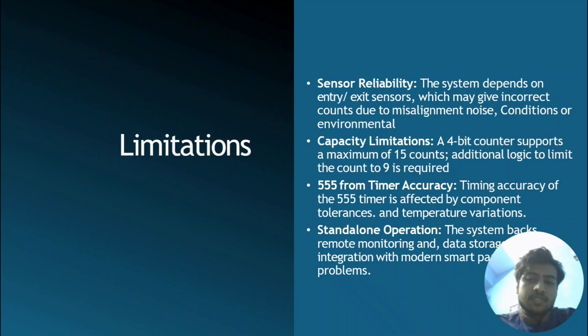Sensor reliability: the system depends on entry and exit sensors, which may give incorrect counts due to noise or environmental conditions. Capacity limitations: a 4-bit counter supports up to 15 counts, which limits the system. 555 timer accuracy depends on the component and temperature control. Standalone operation: the system lacks remote monitoring and data storage and smart problem handling.